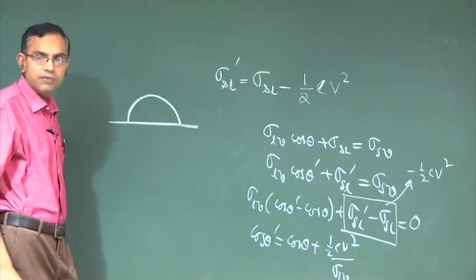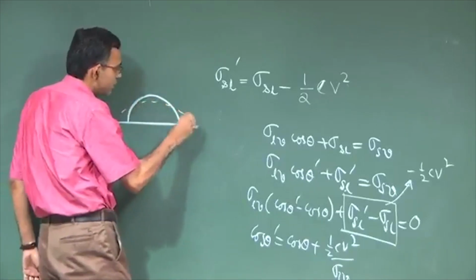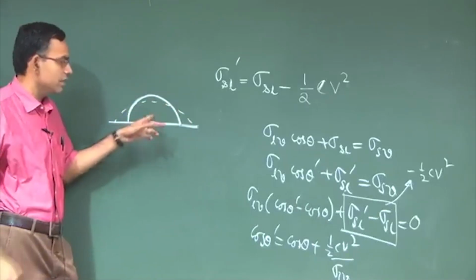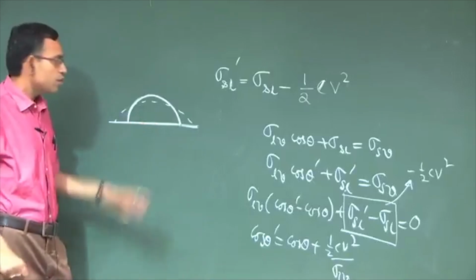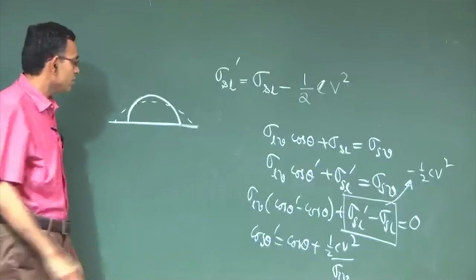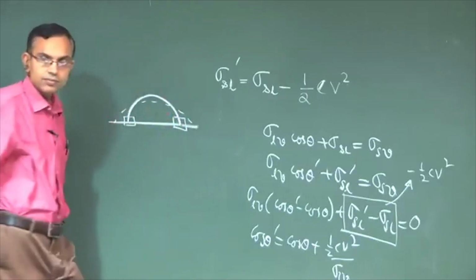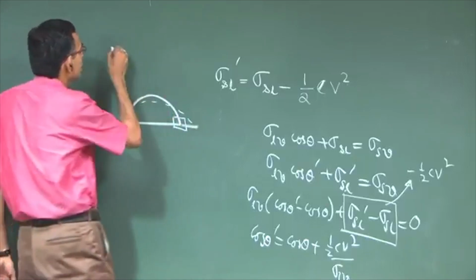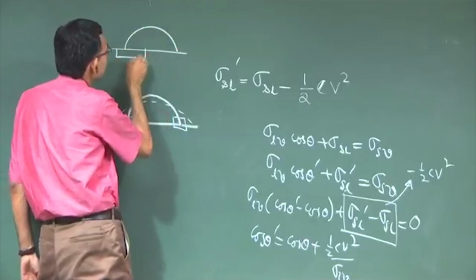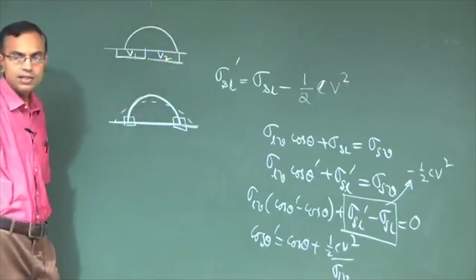Now if you apply electric field, what will happen? Say uniformly this droplet's contact angle will go down, so it will become like this, but this is not moving, this is just spreading. So if you want the droplet to physically move from one place to the other, what you can do? You can create a differential in voltage across the two ends of the droplet. So technically you can put this with voltage biases V1 and V2, where V1 is different from V2.